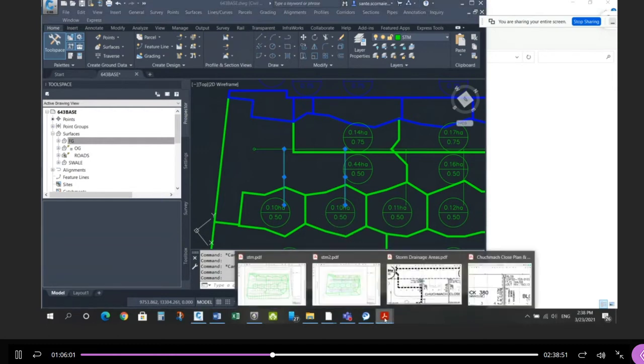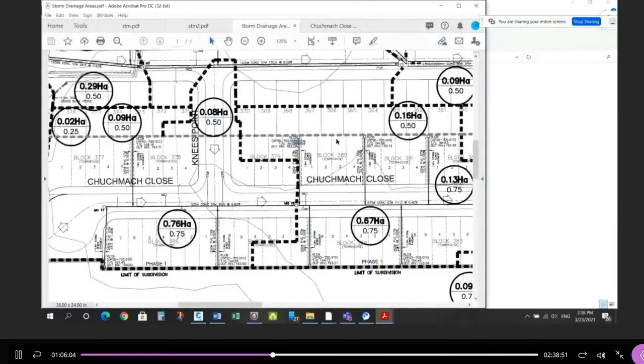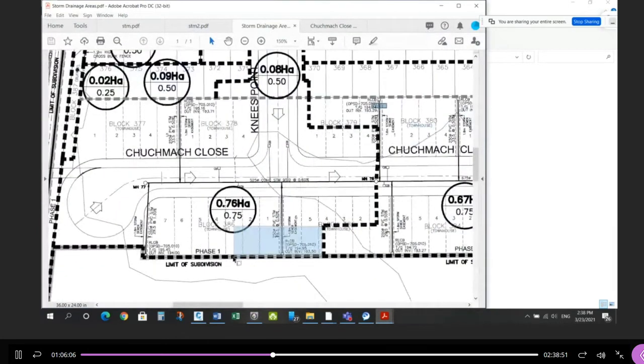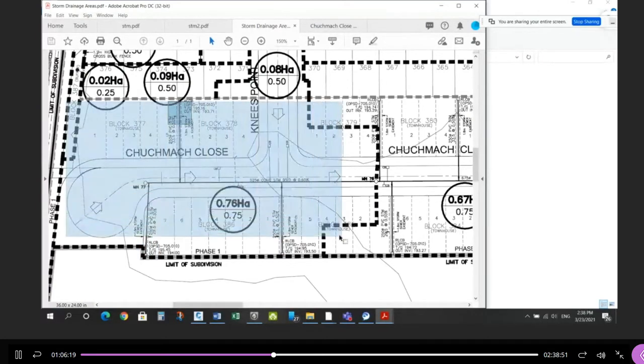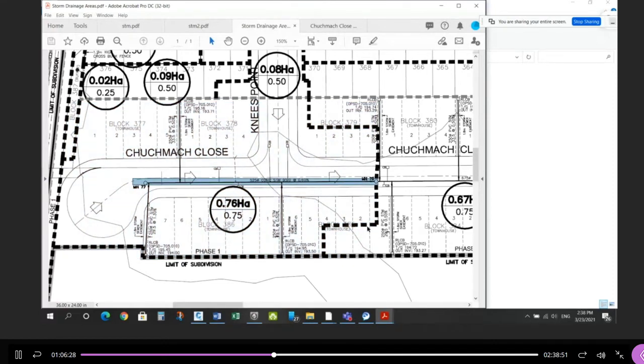Okay. And that's the drainage area that's presented in this subdivision, right? Notice there's no area for this one, right? There should be an area for this pipe. It's not there. There should be an area for this pipe. It's not there. There should be an area for this pipe. It's not there. The area going to this pipe and this pipe and this pipe are all combined into an area that is used to design the street sewer only, 77 to 76. We're designing this only. This is the only line that shows up on the spreadsheet. Rear lot catch basin to this pipe, rear lot catch basin to this pipe, rear lot catch basin to this pipe is not on the spreadsheet. Okay, they combine them and they only design the street sewer.